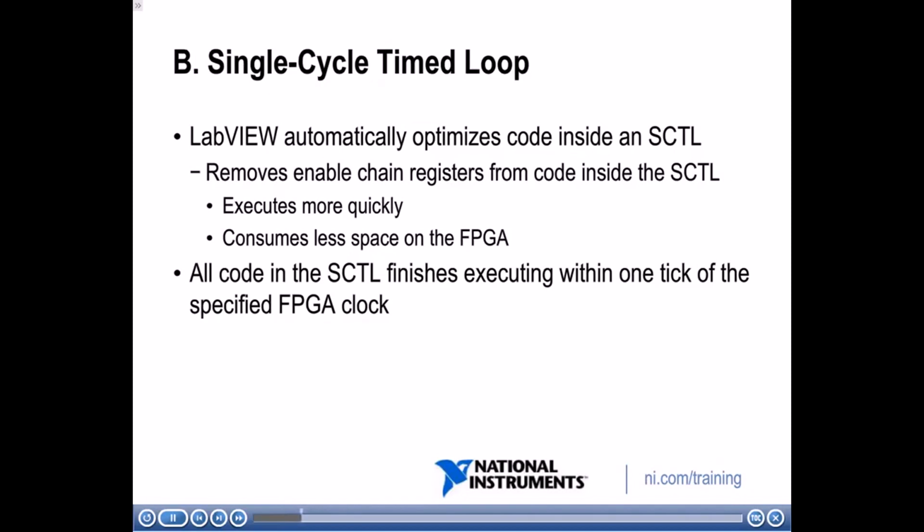So that's a huge advantage that we've seen. We can turn a 12-cycle while loop, by putting it inside a single cycle time loop, and reduce that all the way down to 1 tick. So you can get some significant speed advantages here.